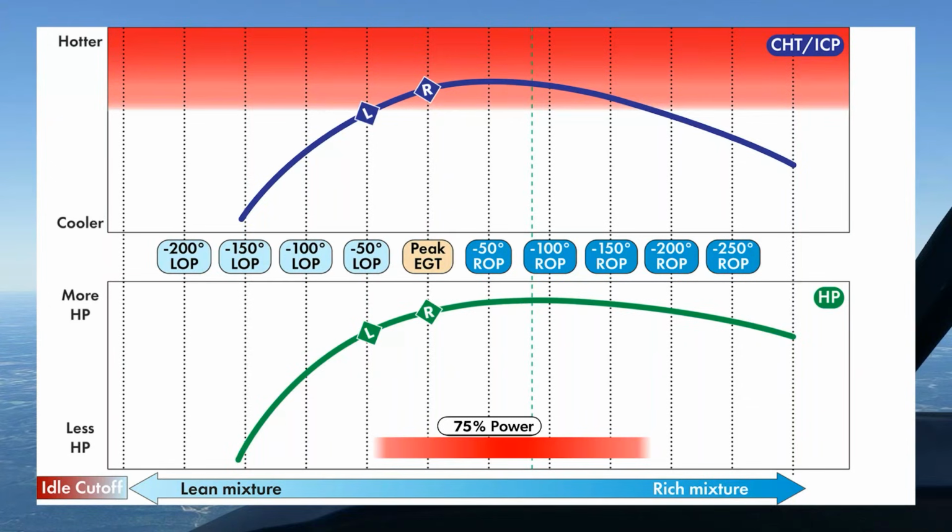in this light, which is you do the same thing. You lean for roughness, you enrich for smoothness, and then just for a bit of extra fuel, a bit of extra cooling, so the saying goes, you enrich by just a few more twists. And you can see why you don't want to enrich a few more twists. If you do this, you want to lean aggressively, get it as lean as it can go.